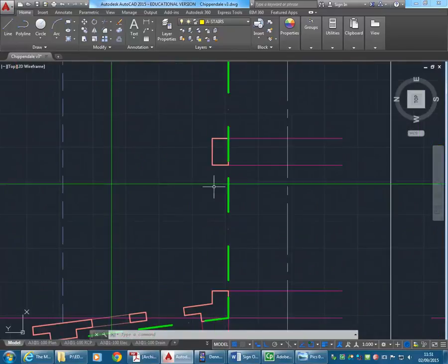You'd have the roller doors cut through here. So I'll let you try to draw roller doors. If you're not sure how to show them in section, just Google drawings of roller doors. They're an easy thing to look up, and quite easy to draw. They really just are a circle with a spiral shape inside.